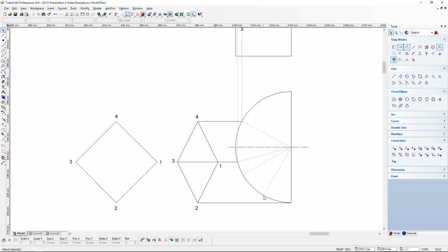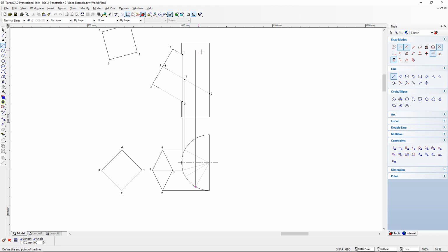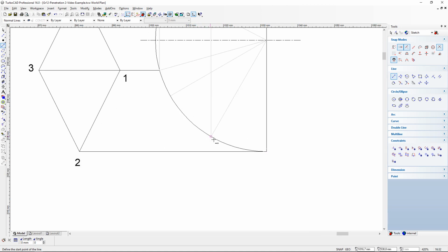So now what I need to do is go to this interval of 30 degrees that I've created, and I now can take that intersection straight up to the front view and draw a light construction line indefinitely, because we don't know exactly how far up we need to go, and then also go from that intersection all the way at 0 degrees to the left, which will then bring me to this point and that point of my prism's edge.